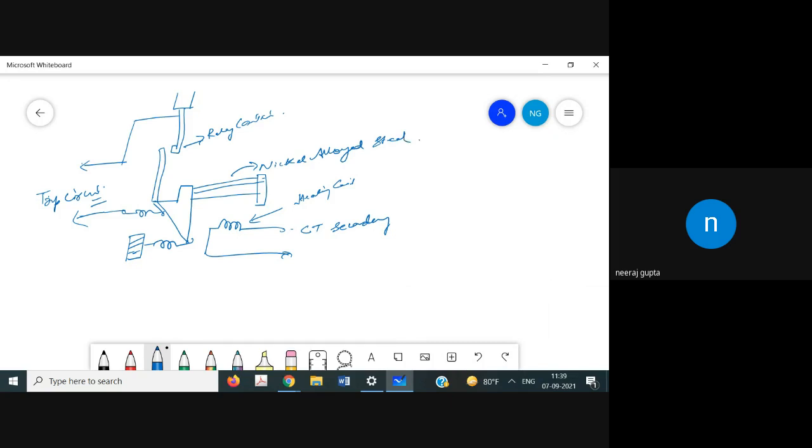These are heated by the element that absorbs the output of the current transformer. Now, at one end of this bimetallic strip an insulated arm with the trip contact is provided, and the arm is connected to the spring which provides the tension against the closing of that particular contact. So this is the basic about this.